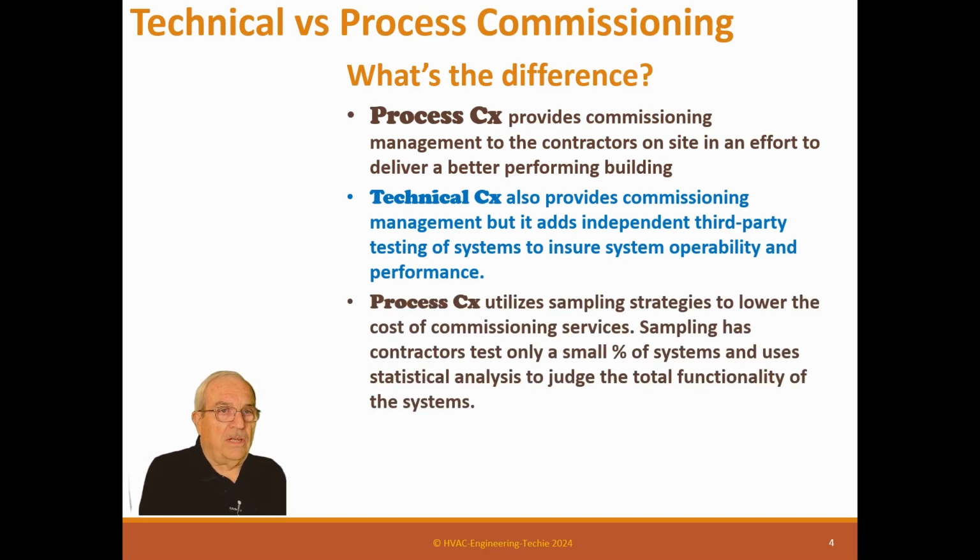Process commissioning utilizes sampling strategies to lower the cost of commissioning services. Sampling has contractors test only a small percentage of the system and uses statistical analysis to judge the total functionality of the system. Now, I understand the science they're using here, but it doesn't actually work.